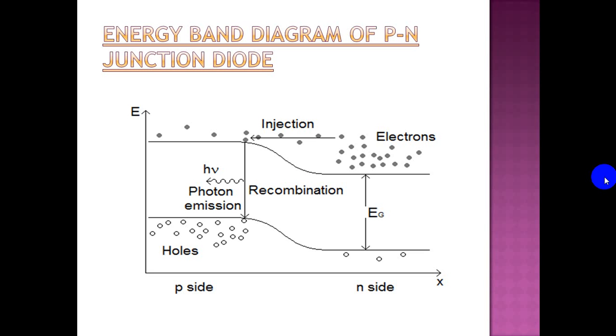The forward current in a PN junction, when it is forward biased, involves electrons from the N-type material moving leftward across the junction and combining with holes in the P-type material. Electrons can then proceed further leftward by jumping from hole to hole, so the holes can be said to be moving to the right in this process.